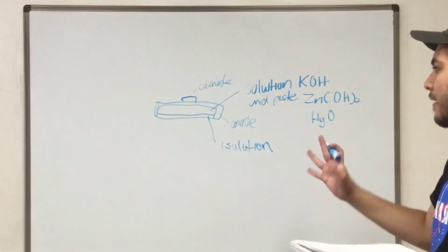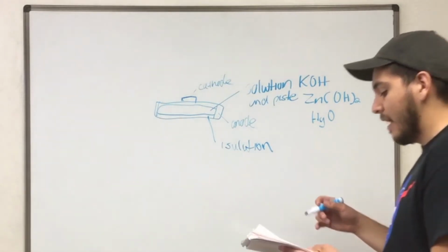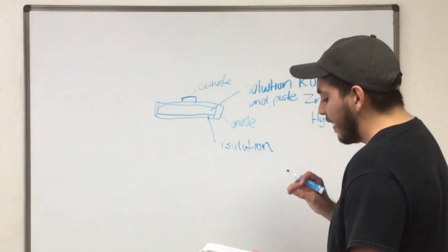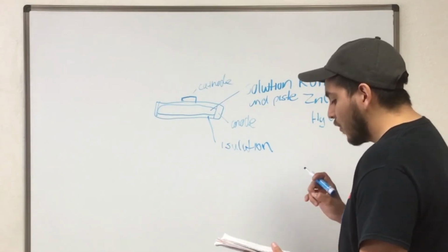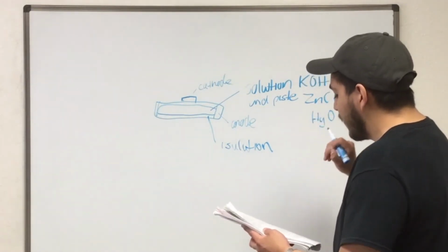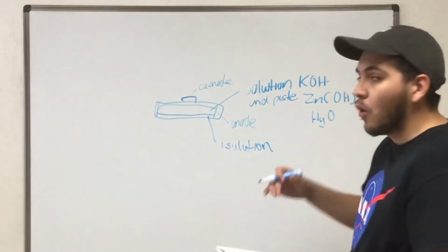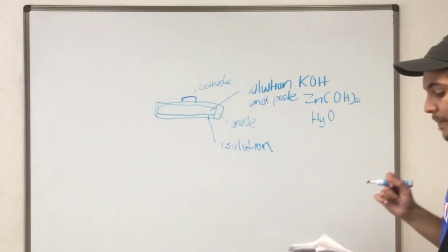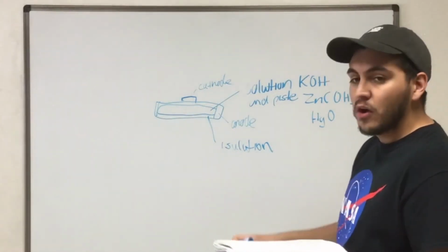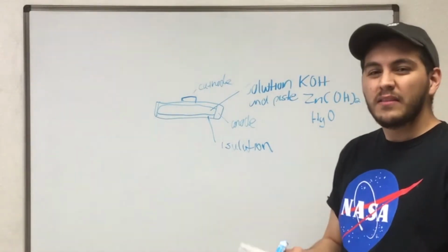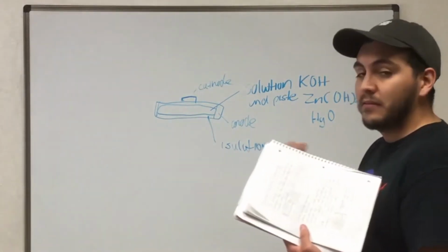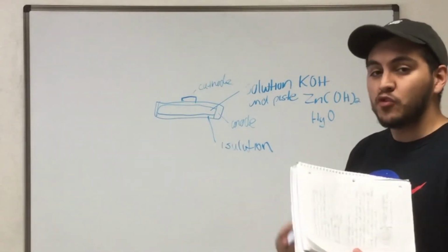Okay, so these are the basic components of a normal mercury battery. It has the alkaline electrolytes that interact with zinc oxide and mercury oxide. This battery provides a more constant voltage and has more capacity and life, like I said. So it's used in medical equipment like pacers, things that are for long-term use. So you don't have to be replacing your batteries like the dry cell batteries.